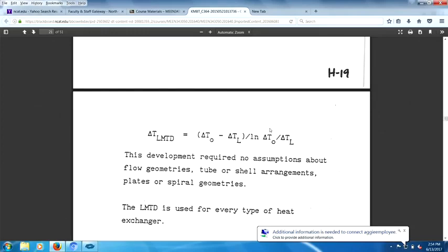What happened was that they didn't clean the heat exchanger sufficiently enough. There was a residue left in the heat exchanger, the used equipment company guys. There's a residue left in the exchanger, and the second company didn't realize exactly how much residue was in there, or what was there actually, and it caused a big kaboom. So the problem with surfaces is surfaces is a first-class pain in the neck, and you can hardly ever get surfaces clean. You got to wash a long time, many times, to get a surface clean.